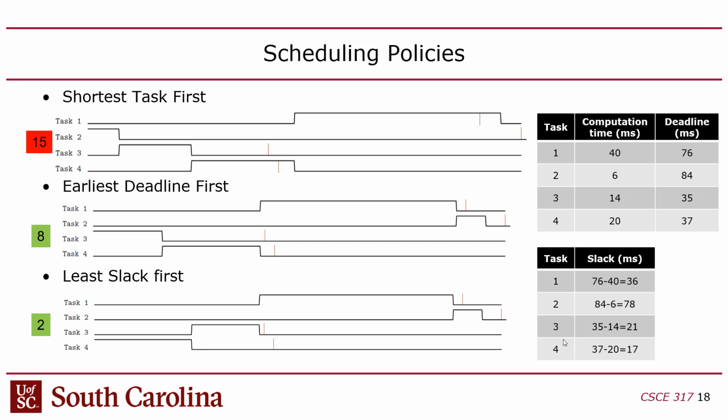So when the deadline elapses, that task becomes ready to run again, and its next deadline will be whatever the period is, added to the end of the current period. You guys with me? This would be just a classic control system where you have a time step. The time step would be both the rate at which you run the task and the deadline. You have to complete the task before the next time it's run, obviously.